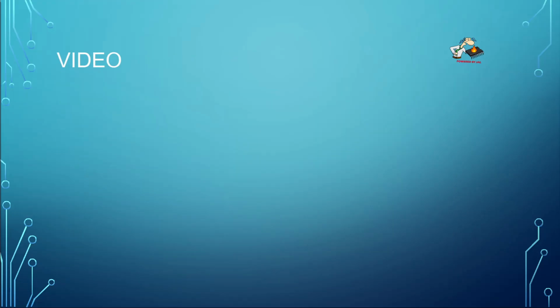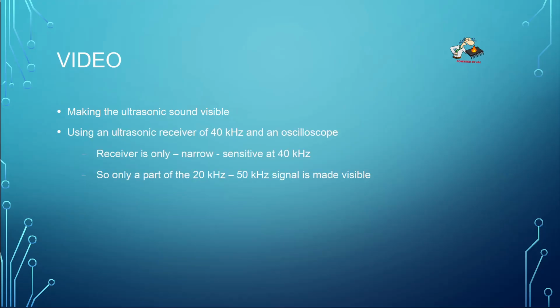In the following video I'm going to make the ultrasonic sound visible, because you can't hear it. For that I'm using an ultrasonic receiver of 40 kHz and an oscilloscope. This receiver has a resonance frequency at 40 kHz, so it is only sensitive at 40 kHz and not so sensitive above or below that frequency. So you will only see a part of the whole spectrum of 20 to 40 kHz, only the 40 kHz signal is seen.